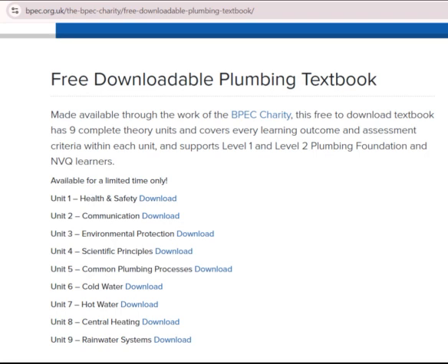Each of the materials that we have just identified have specific applications within the plumbing industry. Look at the table below. The applications of materials. Material type, application. Metals. Copper: tubes and fittings, heat exchangers. Brass: compression fittings, boiler components. Bronze: heat exchangers where the risk of corrosion is high, secondary circulation pumps for hot water systems. Gunmetal: compression fittings and boiler components where the need for corrosion resistance is required.